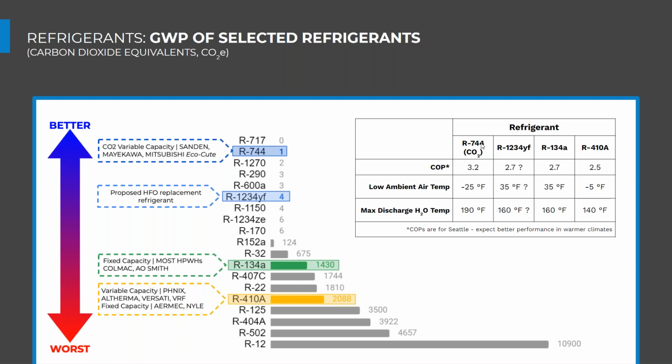We also have higher COPs typically with those CO2-based refrigerant systems than our R134A or our 410A, which you can see there. Now the 410A, there's a huge benefit because we can operate them down to low air temperatures, just like our CO2 refrigerants. But our R134A, right, they're challenged by that low air temperature. So please be aware of that in your system selection or the equipment selection for that heat pump water heating system.